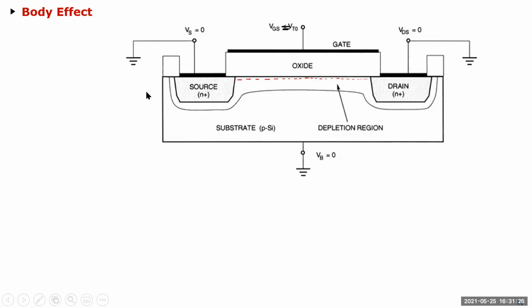For example, when you do combinational gates, your NAND gate will look something like this. So this is A, this is B, this is your VDD, this is your output, and your NMOS is two series devices. So this is a NAND gate, right?